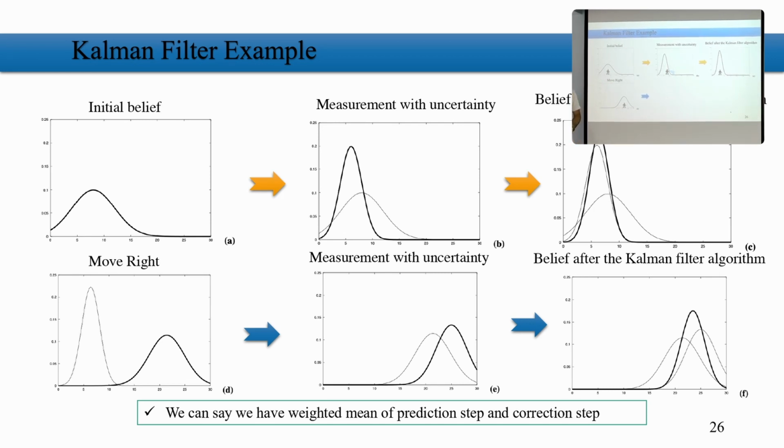We said, okay, if your robot is going a little bit to the right, if you want to go there, you end up there. This creates curve and more uncertainty during the movement. And because of that, in Kalman filter, observation tries to correct our belief based on that. Okay, we say after some movement, robot again sees, and after the seeing, we have another curve, this one over there, and Kalman filter again updates the new belief for us.